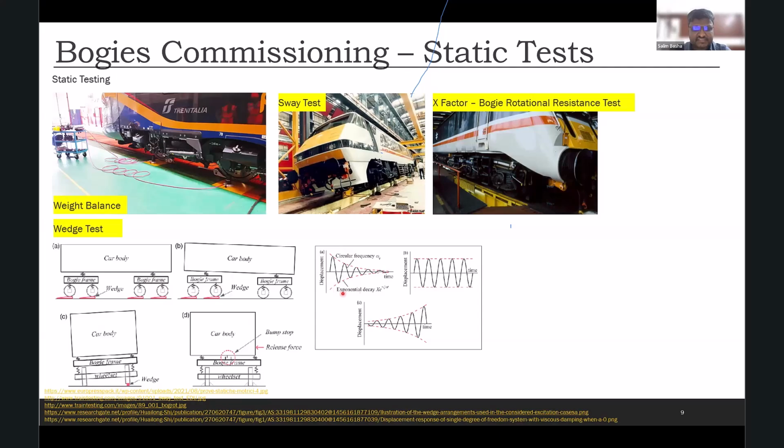It should show this type of a scenario wherein it's going on a track at a good speed, and then there is some disturbance on the track. So that disturbance should not make it oscillate. It should damp down after certain cycles, like this picture shows. We don't want this type of a scenario. So here we try to induce those modes.